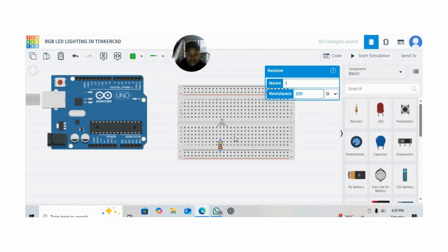Now we have already set our resistor there. We can now proceed, maybe do powering or connect these terminals to the digital pins of our microcontroller here, and those pins should be between digital pin number 2 all the way to digital pin number 13, because we are obtaining an output from this, and that output is light.